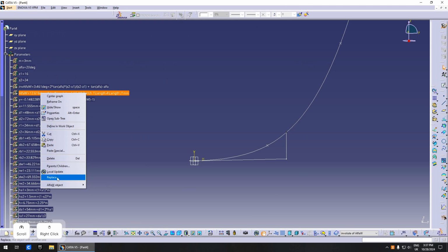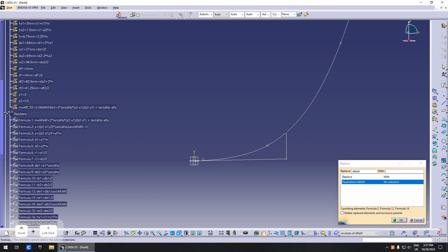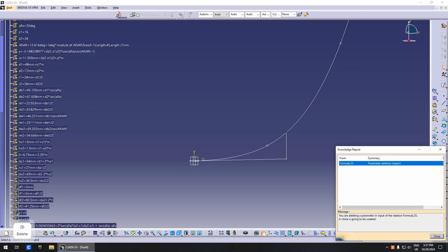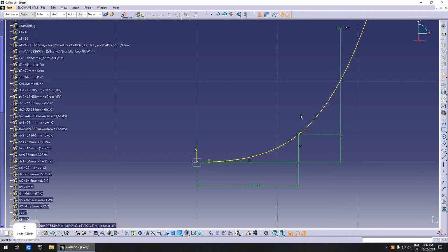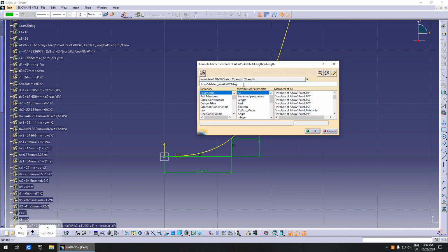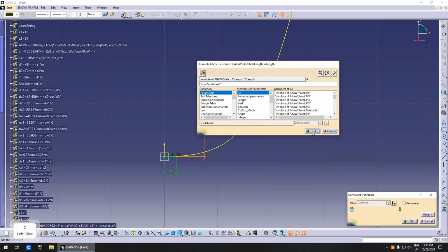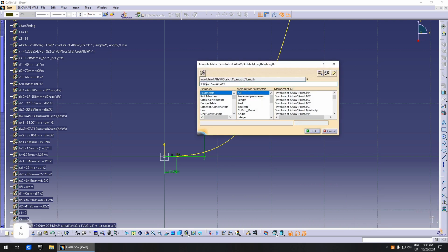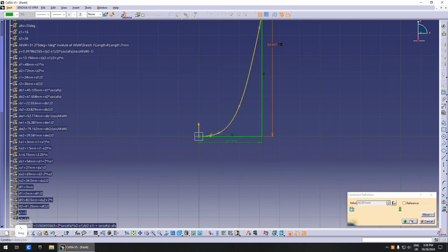And I guess we can just replace this parameter with this one. No, it doesn't let us do that. That's unfortunate. We would have to then delete this. Here where we have the involute, we need to link this to the new parameter. Now we don't divide it by degrees anymore, and it's like 0.006, which is very, very low, and that's why it needs 1000.